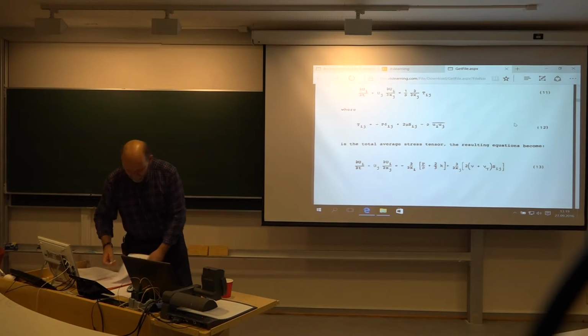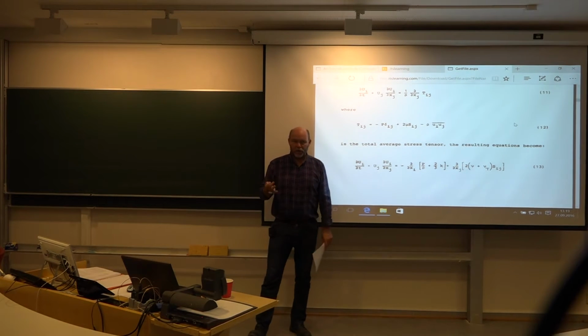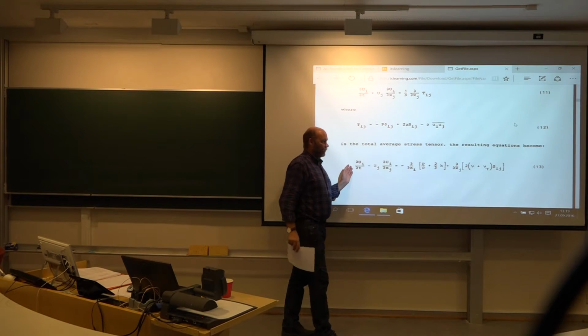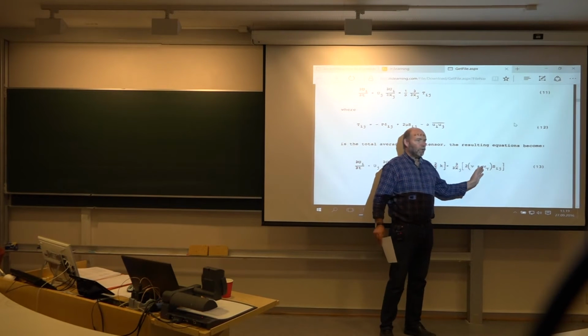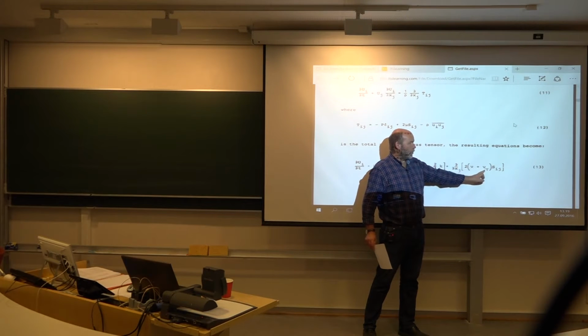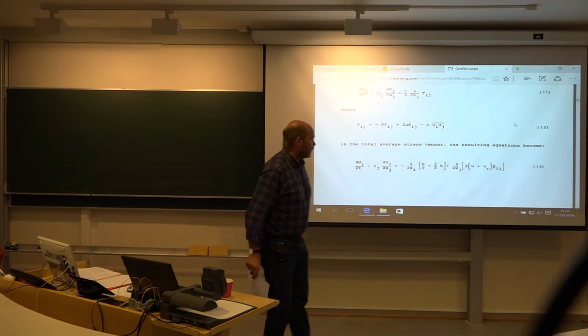But inside this family of turbulence models, the simplest one was the zero equation model. No transport equation, except the Navier-Stokes, of course, but no transport of any turbulent quantity. So there you will just use some algebraic equation for this guy, like Prandtl's mixing length, which is the most famous one. It actually works, but only for very simple problems.